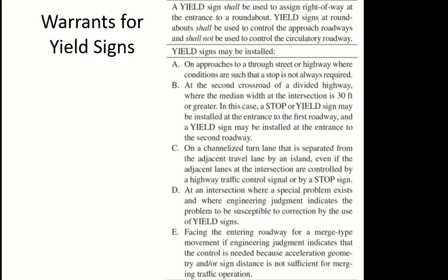When you have a roundabout, the yield sign is assumed to be there at the entry. So all entries to the roundabout have a yield sign, as you mentioned that we need to give priority to the vehicle which is already on the roundabout. So there's a yield, give way. The conditions which you see here are other than that.